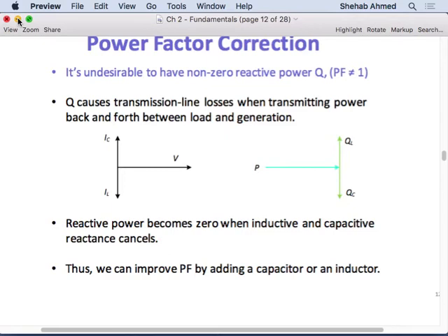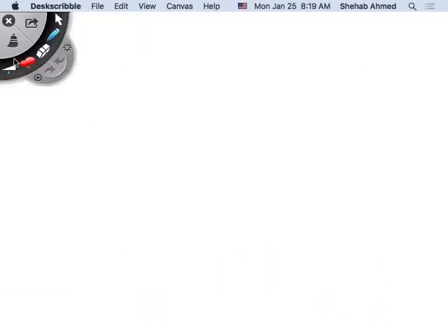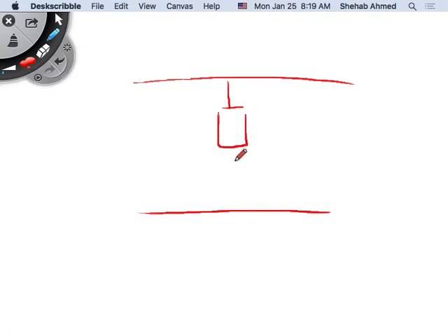And then the other solution is to add capacitors using power electronics. That's the best thing to do, but it's the most expensive. We studied that a little bit in 438 last semester, and it's basically simple. You have a capacitor, and before this capacitor, for example, you add a box. This box needs to be able to control when the capacitor comes in and out of the system. So how would you do that? Let's say you add a thyristor. What's a device called a thyristor, for example?